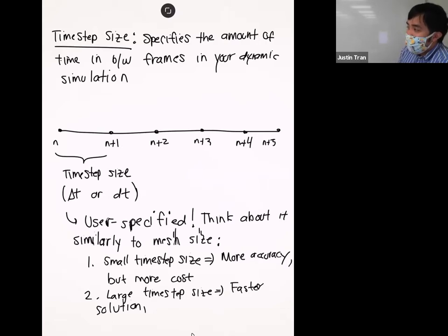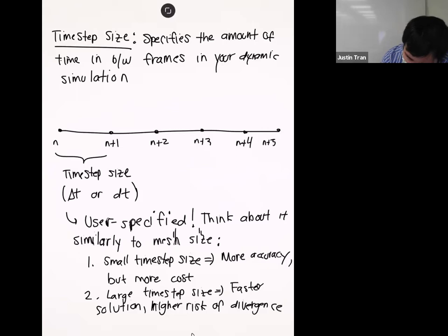And also, the whole thing might just blow up. And so there's an added risk in dynamic simulations called divergence. When your simulation diverges, what basically happens is that all your solution variables just tend to blow up. So for the deformation, you get some astronomically huge number. For the stress, you get another. And you get numbers that are obviously way too high for what your simulation is.